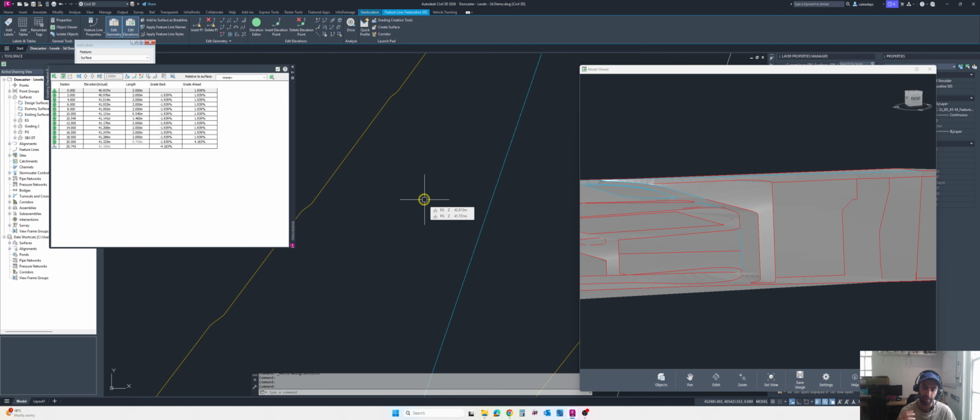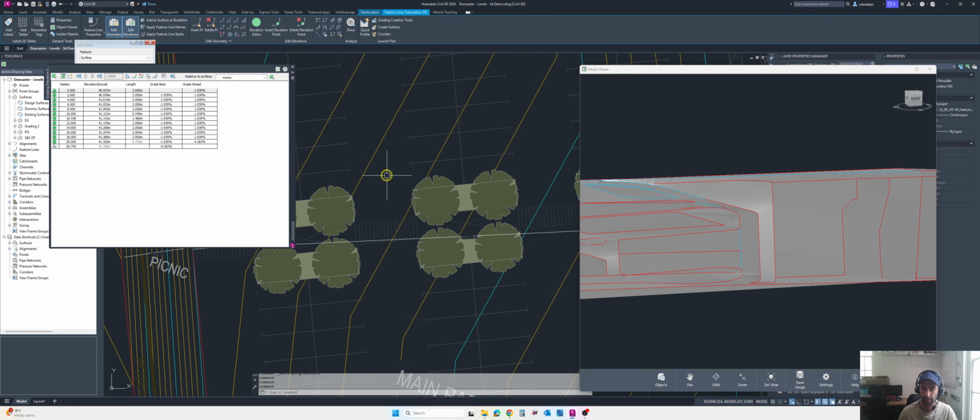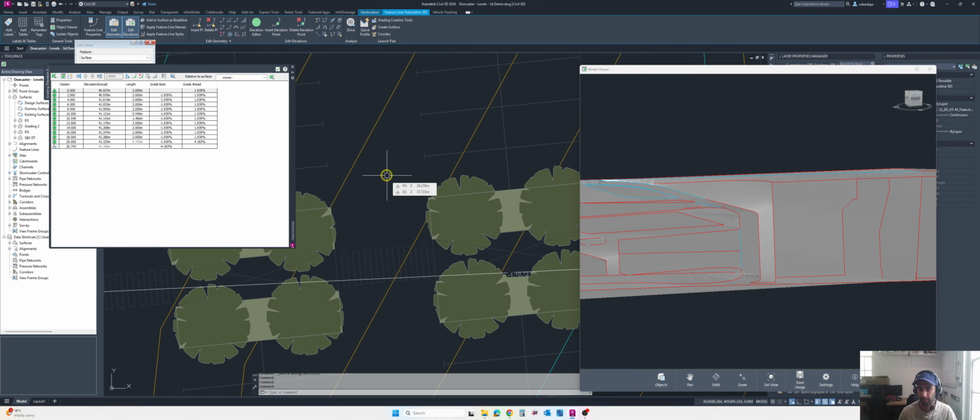So this is extra. We have to try to balance our site with cut and fill. Obviously it's not possible to do 100%, but it's better to work it out one by one. For example, here I have a 100 millimeter cut, and I will try to achieve a fill here. You can see the PG here is like 1.5 to 2 meters above the existing ground. So we can utilize the cut from there here, or in the green areas. All of this grading is to make an economical, sound platform for the construction phases.